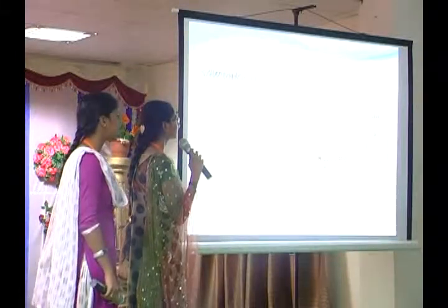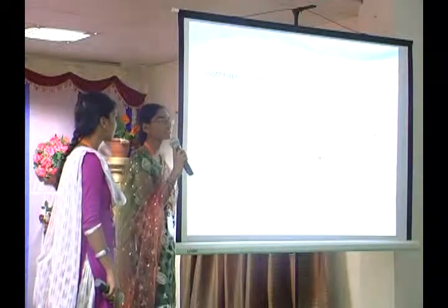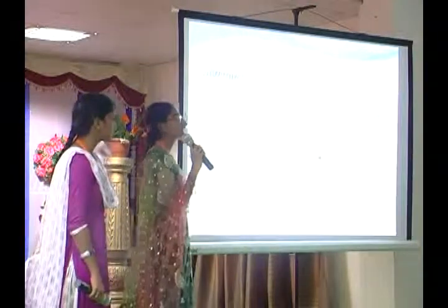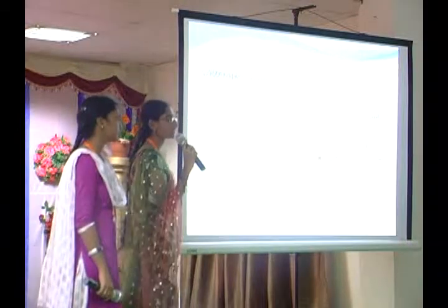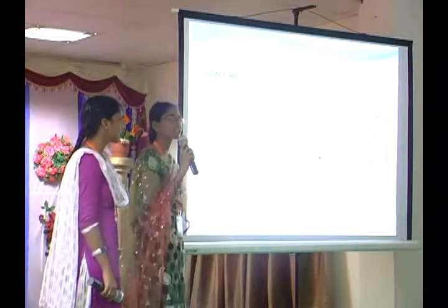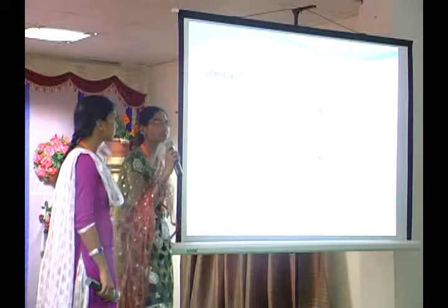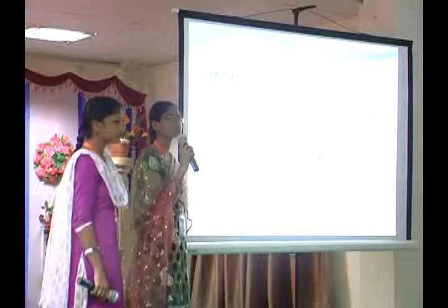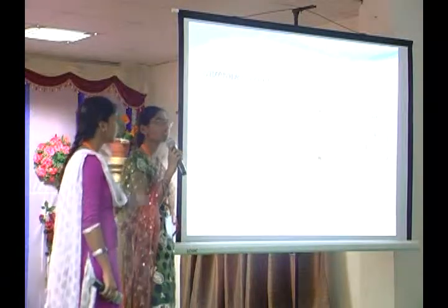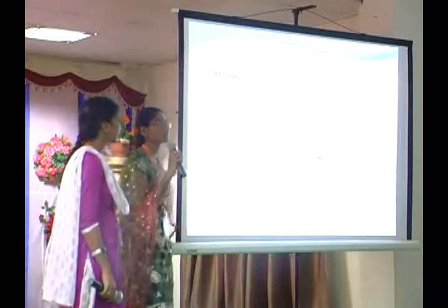SAW touchscreen. SAW means nothing but surface acoustic wave. It always depends on the waves which are present on the surface area. If it touches the screen, the surface waves are absorbed by the screen. It is usually constructed of pure glass with piezoelectric transducers.